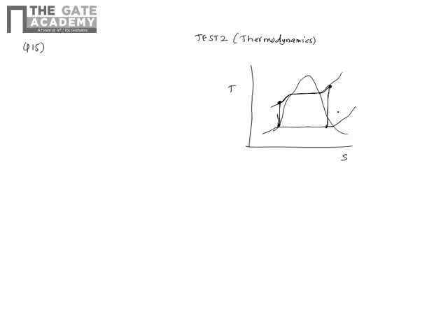So at the end of the turbine you will have water, some part with some dryness and some part as liquid, and then in the condenser it will give out some heat and finally become the saturated liquid. So this is 1, 2, 3, 4. This is what happens.